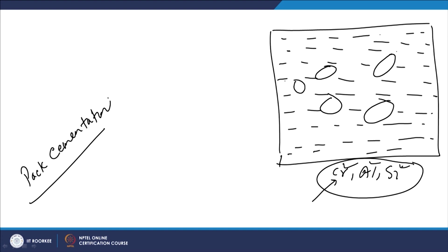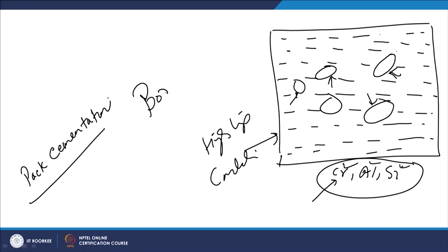The powder particles which are in contact with the components whose surface is to be modified, under suitable high temperature conditions, these elements diffuse into the surface of the component and change the composition of the surface and near surface layers. Boronizing is one typical example of this kind of pack cementation.